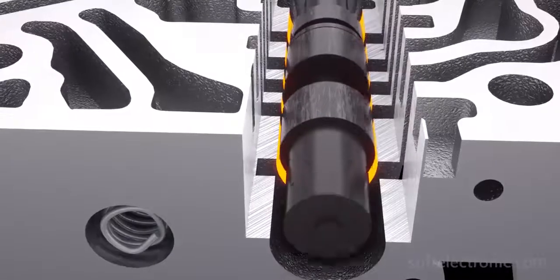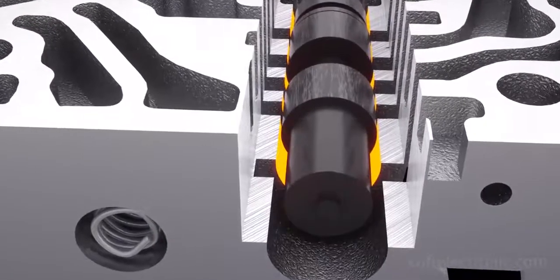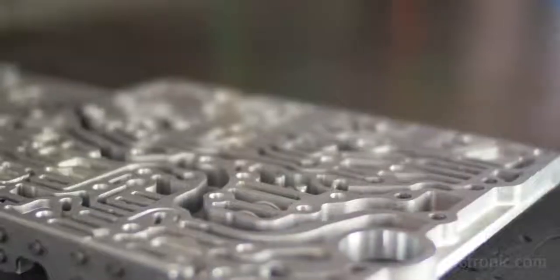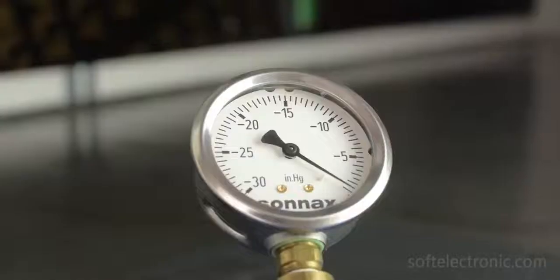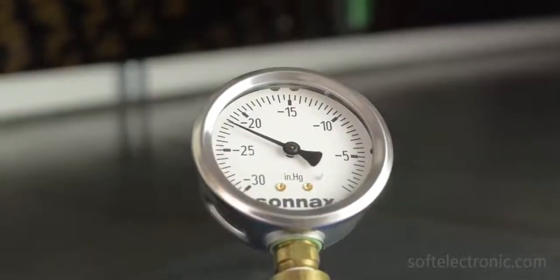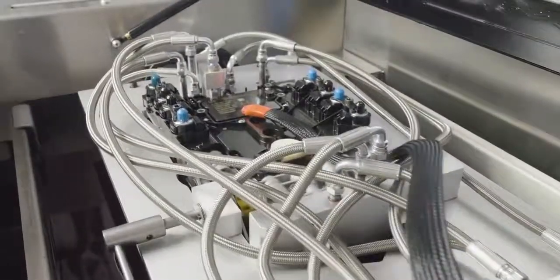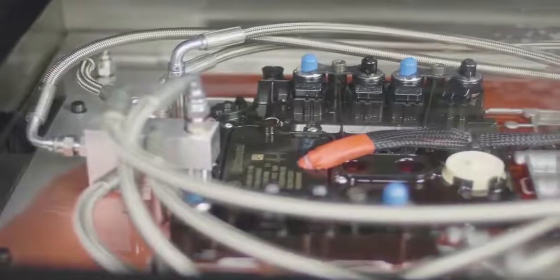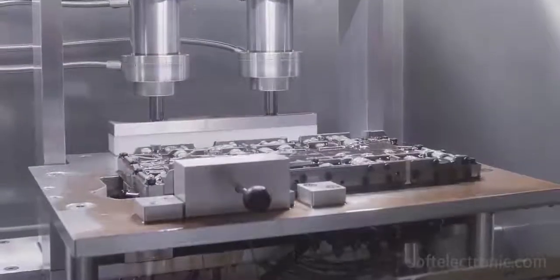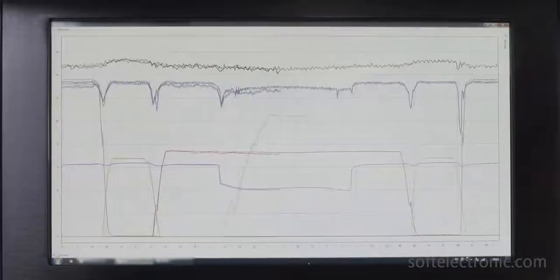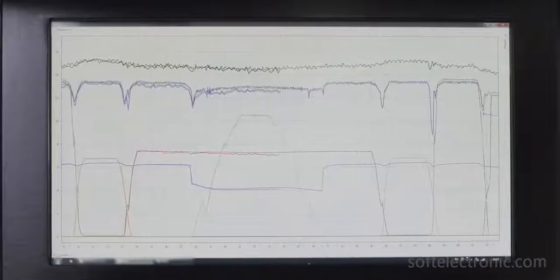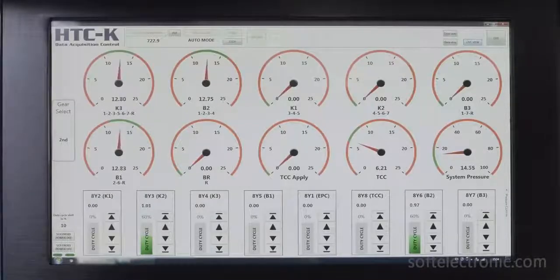To determine whether there's wear in the valve seats, 2 tests are performed. The first one is by a vacuum machine, performed manually for each valve. The second test is carried out on specialized high-tech stands, which simulate the pressure and hard working temperature of the valve body in real conditions. The correct or incorrect operation of each valve is determined with the help of charts.